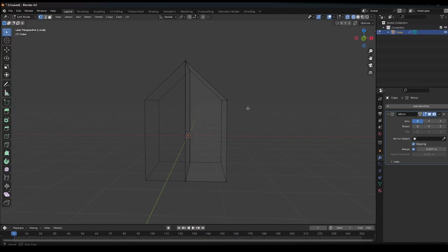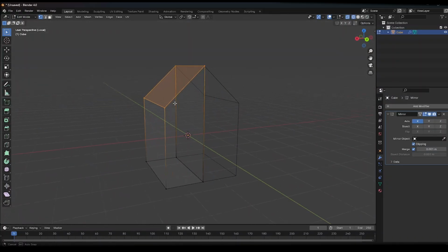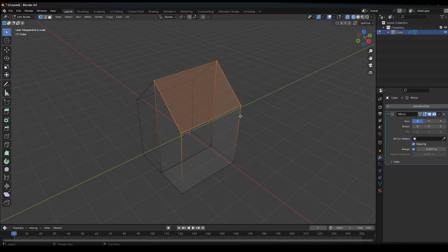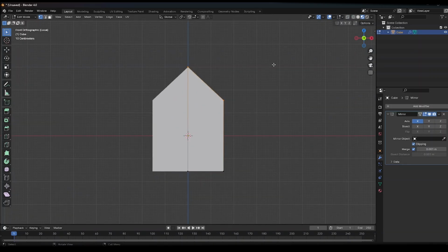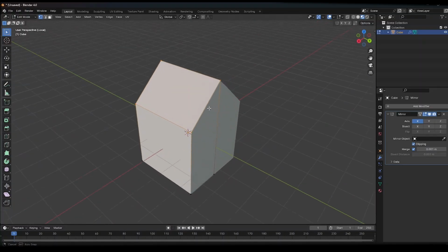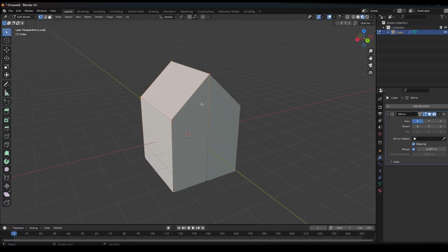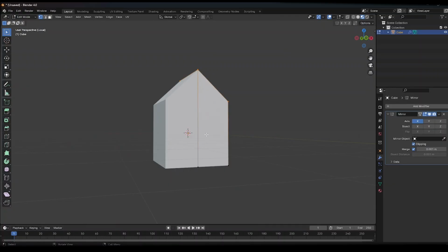Only in wireframe, whenever I am selecting, I'm just going to press 1, and if I press B and select the whole thing, the whole face of the top part will be selected at once. So all of those viewing angles and different types of views also help you in your work. You can see now only the front part is selected. Press B, try selecting, and if you have a bit of corner on it, then it will select the whole face. Let's say wireframe mode is going to help you select the whole face of the top part or the part you've selected. Okay, so make sure to keep that in mind and try using it however you want to make your work a lot easier and speed it up.